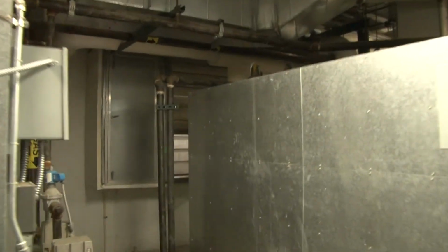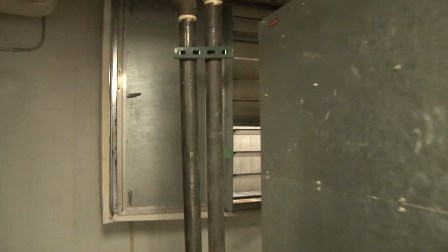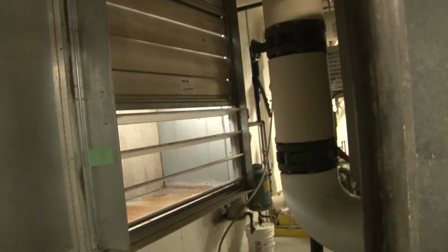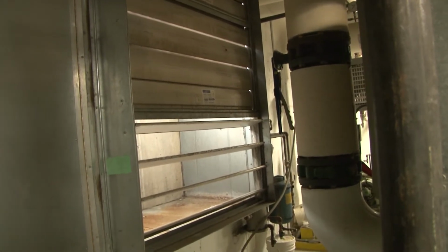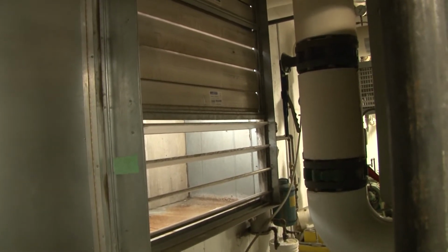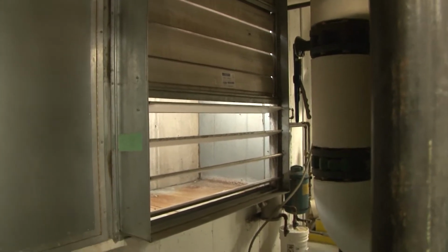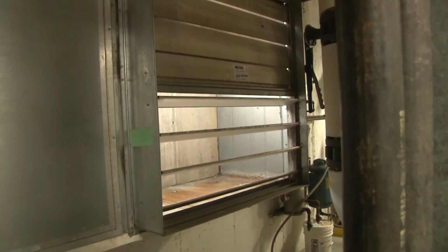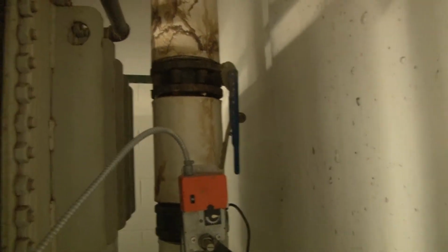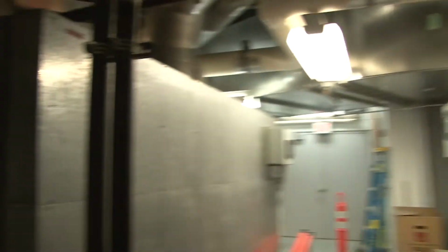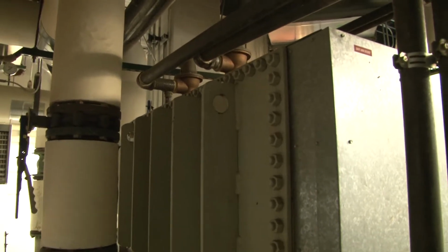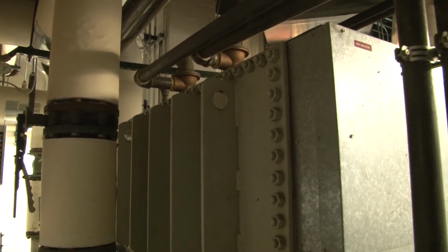If we go to the back, we can see our combustion dampers that will open and close based on the call received from the system and allow combustion air to go into the mechanical room and provide combustion air for the combustion process inside the boiler. In the back, we can see our different valves that control the flow of water in and out of the boiler. Same thing for this boiler, and we see our relief valves that will open when there's an